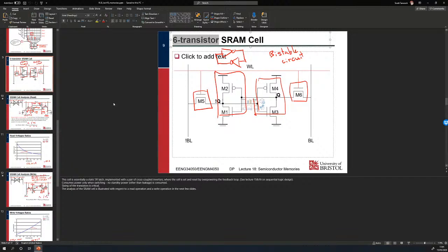So while flip-flops are suitable for registers, the register file, or little pipeline registers, if we try to pack a large number of them into a small space, we're going to find that we don't have enough of them. And so when we're doing our level 1 and level 2 caches, we use 6 transistor or similar SRAM cells because they're smaller, so we can get more of them into a certain space.